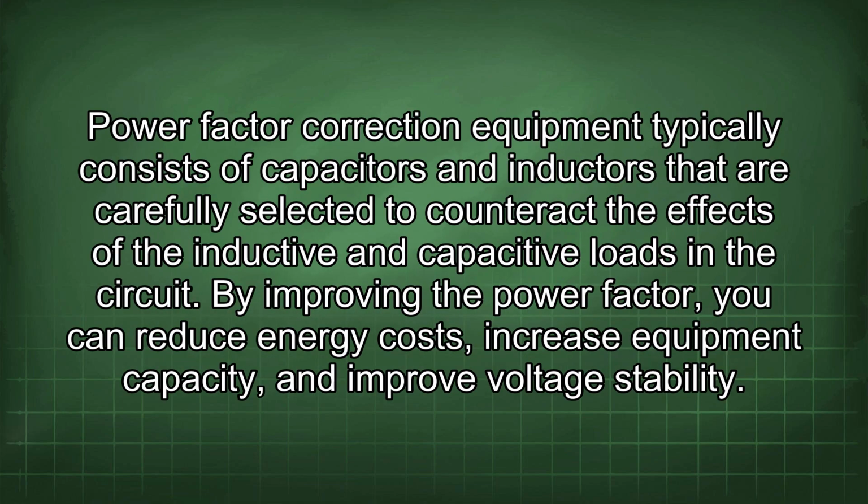Power factor correction equipment typically consists of capacitors and inductors that are carefully selected to counteract the effects of the inductive and capacitive loads in the circuit. By improving the power factor, you can reduce energy costs, increase equipment capacity, and improve voltage stability.